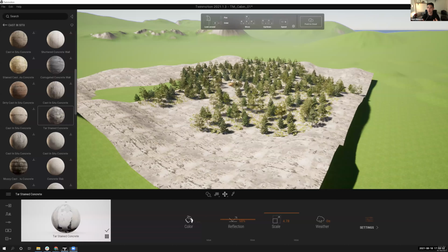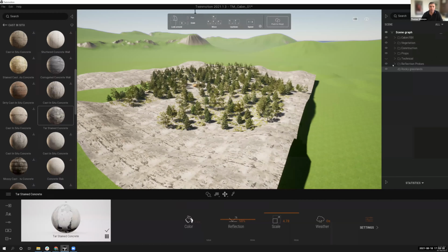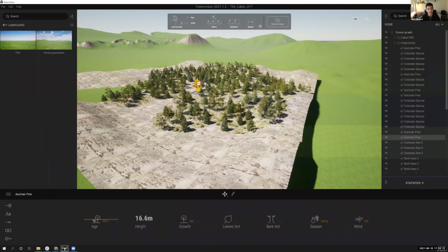Can you elaborate on the phasing portion in Twinmotion and how that happens? So the phasing that I was talking about was in Twinmotion, which I can showcase. Matt, do you do any phasing in Archicad? A little bit. We do a few renovation projects, but it sounds like they're excited about the phasing in Twinmotion and whether you need to build that in from your initial Archicad import, which my understanding is not, that whatever Archicad model you send in, you can completely control the phasing separately in Twinmotion. I don't think that's linked from Archicad, but yeah, in Archicad you can certainly do it with layers and other means to control phasing. Yeah. Gotcha.